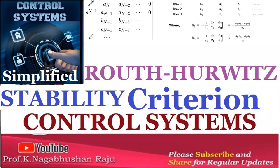Now, if you find the location of the poles by solving the denominator polynomial, which we normally call the characteristic equation of the transfer function, then if all poles lie on the left half of the S-plane, we call the system stable. For a quadratic equation, we can solve it easily. Probably even for a cubic equation, with some difficulty we can do it. But as the order of the characteristic equation increases, it gets increasingly difficult to find the location of the poles. And that's exactly where the Routh-Hurwitz criterion comes in, with which we can determine the stability without solving for the poles.